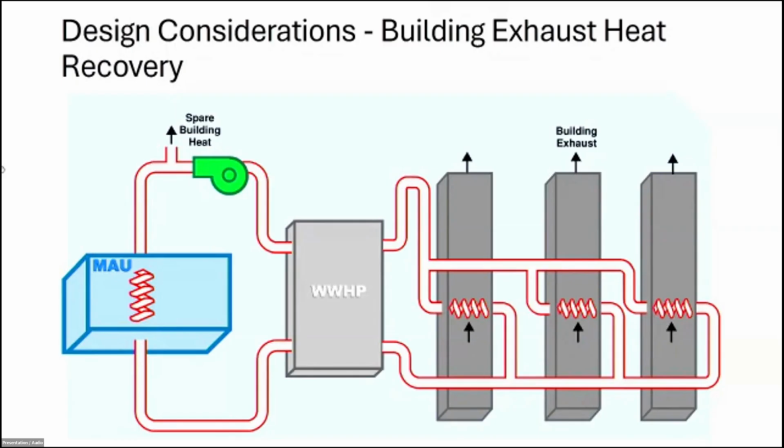So GEDO, they're going to get hit with fines soon because they're putting out too much carbon according to the regulations. And they might have to put people in hotels because they can't keep their domiciles warm enough. So what I'm helping this engineer do is work on two main energy recovery systems. The first is this runaround loop to leverage a water source heat pump to run a chilled glycol loop through exchangers located in the exhaust ducts and pull all that energy that we can over to the makeup air unit.